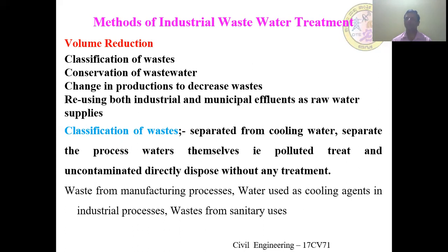That means you are going to separate the wastewater at the source. Separate the cooling tower water, separate the process water themselves. That which is polluted, treat, and uncontaminated, dispose directly without any treatment. Otherwise, it is going to burden the treatment plant.